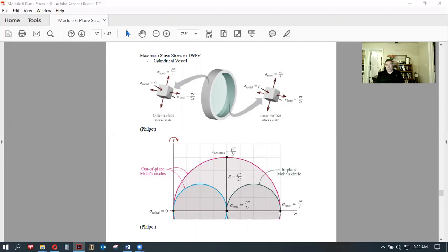And so the normal stresses don't get bigger, but wait a minute, the max shear stress all of a sudden got much larger. Before, it was about PR over 4T, and now it's PR over 2T. It's twice as big. So if you have a material, as ductile metals are, that are sensitive and usually dictated by shear in their ultimate failing, you stretch it out, you actually have a max shear stress on the 45-degree plane, and that can be a critical one. It's actually failing in shear, even though it's a tensile kind of behavior.